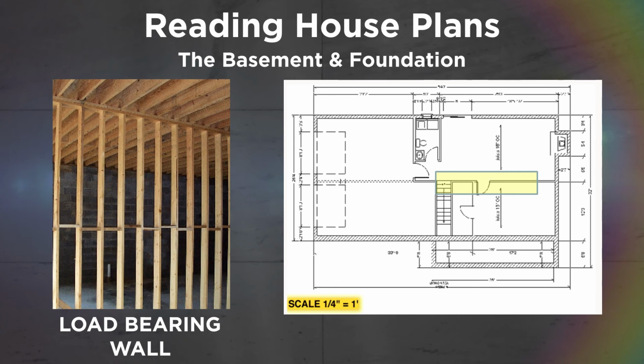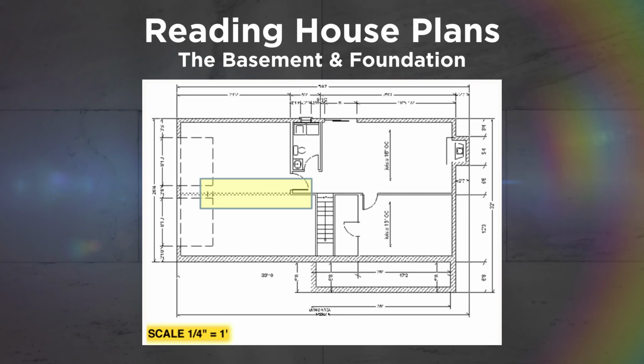Once the wall is in place, it would look like the wall in this photo. At the top of the wall, floor joists are resting on top. This is an indication this will be a load-bearing wall. More on this later. The wall in our plan will not run the full length of the house. Instead, it will stop once it reaches the garage. Inside the garage, the wall will be replaced with 2 steel columns that will support the remaining floor joist.